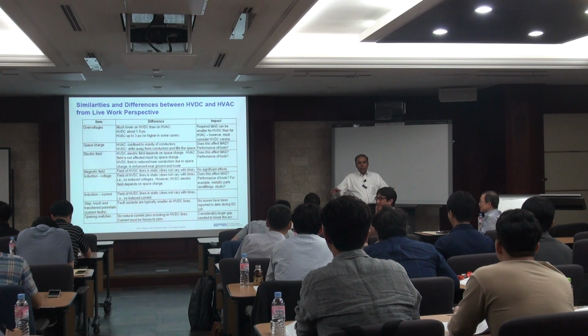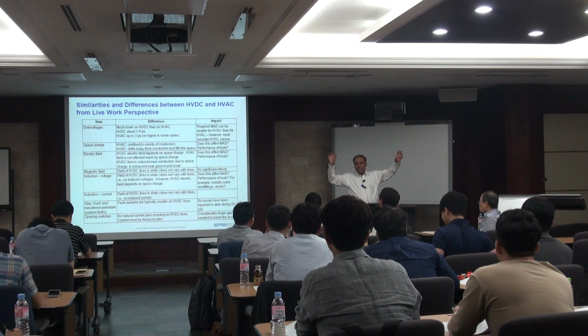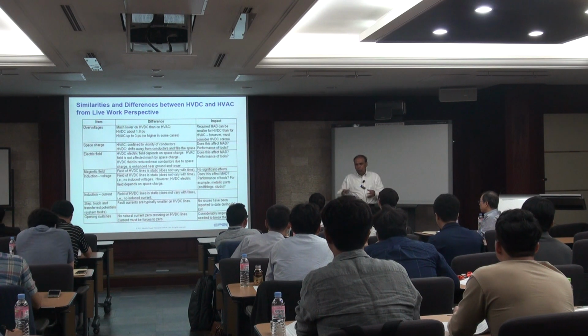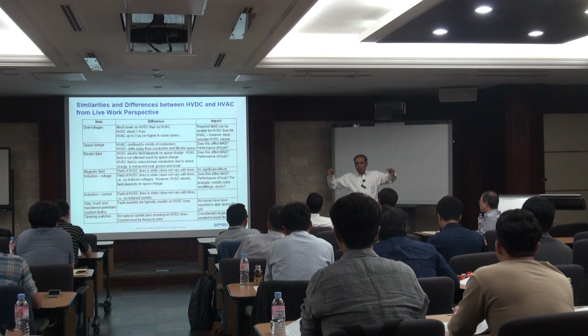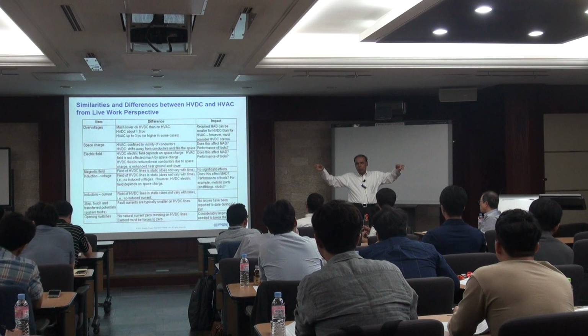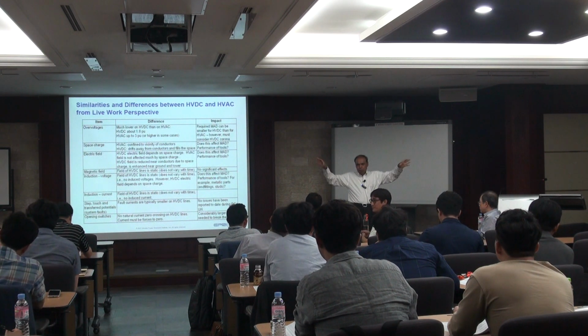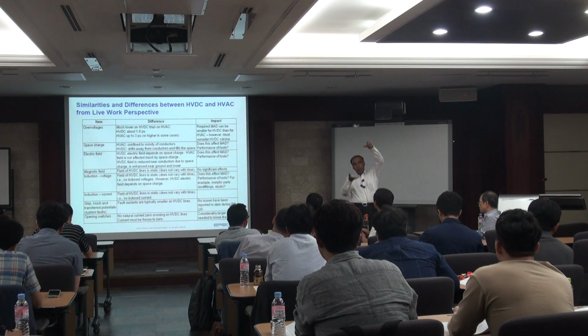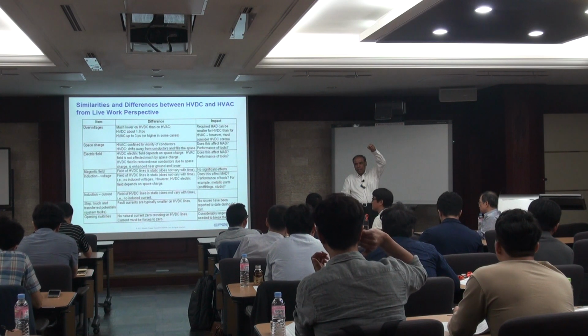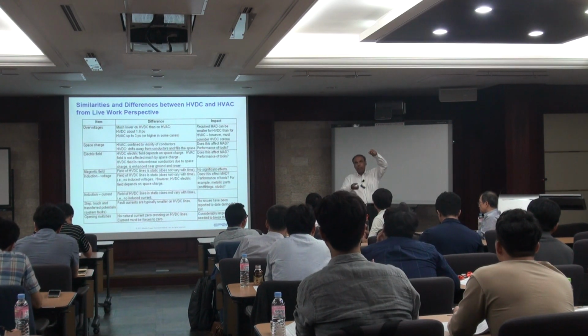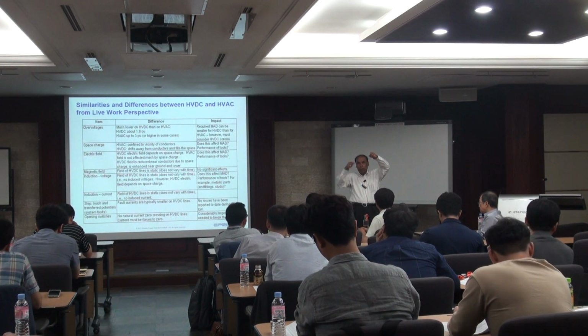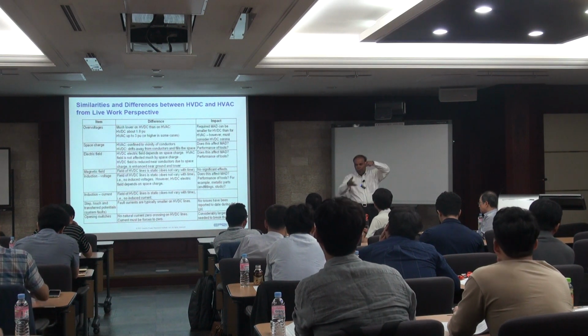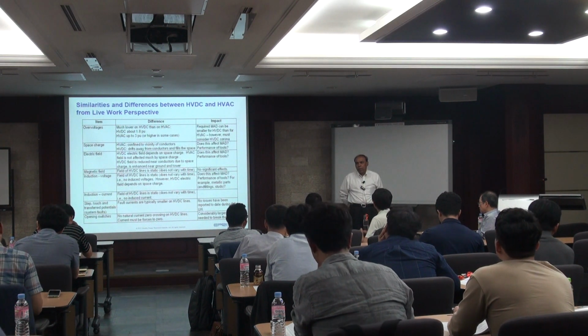Suppose, say you have 3 conductors, AC conductors, you are converting that to DC, which poles you want to use, like the outmost poles, positive, negative, or vertically, you have 3 conductors, 3 lines, you're converting AC to DC. You put DC positive on the top or DC positive in the bottom. That will have a different corona performance.